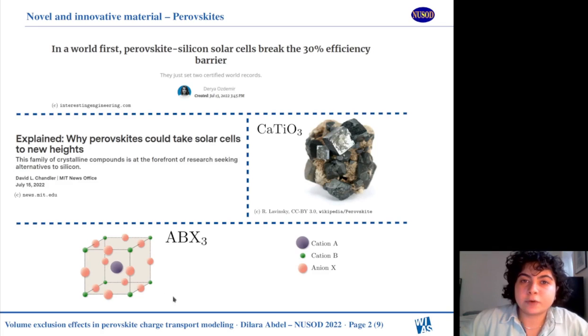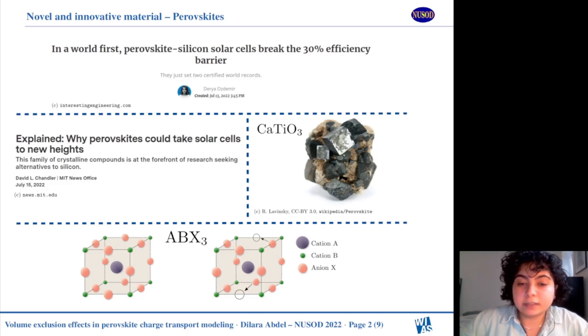In reality, crystal defects occur that dynamically appear and reappear. They leave void spaces within the perovskite crystal structure, called vacancies, which can be occupied by the ions. This permanently changing crystalline structure affects the electric charge carriers. Thus, researchers agreed that besides the movement of electrons and holes, we have additional ion migration, which plays a major role. So for formulating an adequate model, which additionally incorporates this phenomenon, we use a drift-diffusion